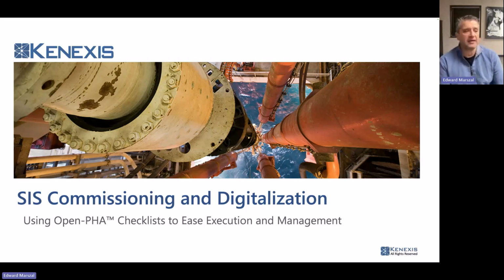That means that people in the office who have experience and know what they're doing would write specifications for what the instrumentation's supposed to do. And then I would grab a pile of specs and a pile of drawings and a pile of standard worksheets and get on a plane and fly to wherever they built the plant and make sure that what was installed is what was specified. And that's kind of the beginning and like one of the most important parts of commissioning.